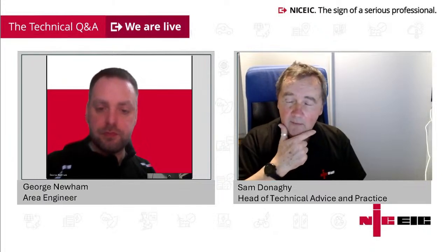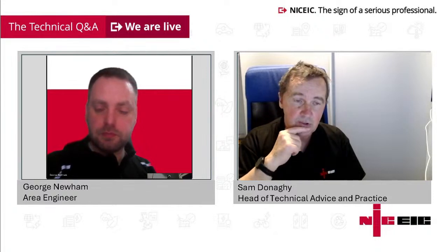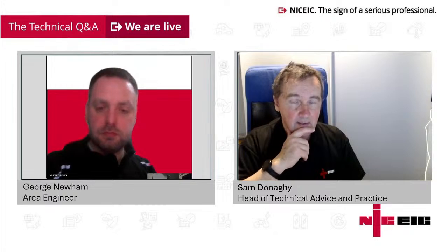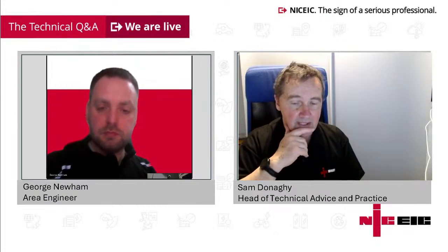So I think it's key. I'm pretty sure there are manufacturers who are already putting out a standard 116 amp board, so we've got the general DNO 100 amp plus 16 amp of self-generation capability. So that's worth it.